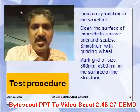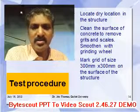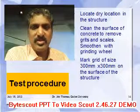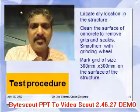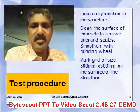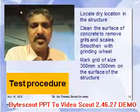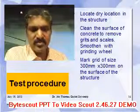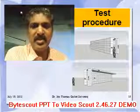In the test procedure, we have some steps to be followed. It is listed in this slide. Locate the dry location in the structure where the tests need to be conducted. Then clean the surface of the concrete to remove the grits and scales. Smoothen with a grinding wheel. Mark a grid of size 300 by 300 mm on the surface of the structure. So in this figure, it is shown in a wall structure how it is being done.